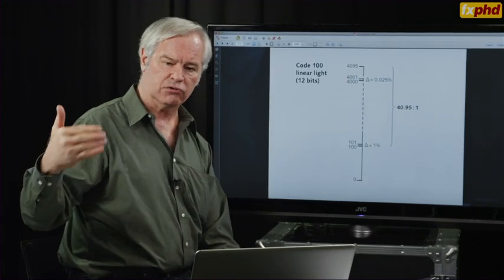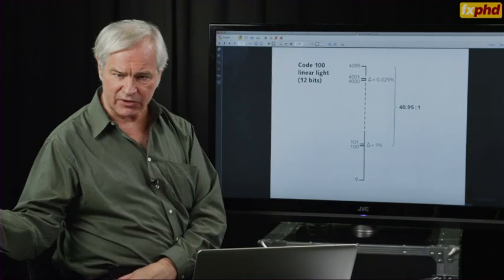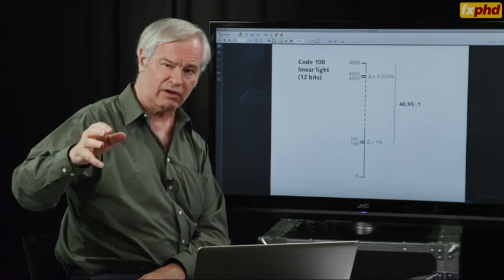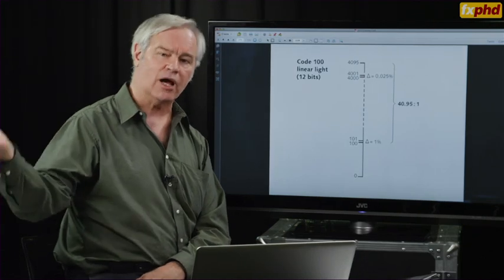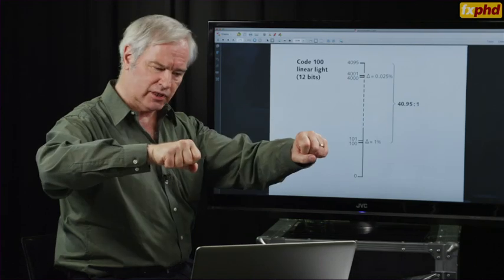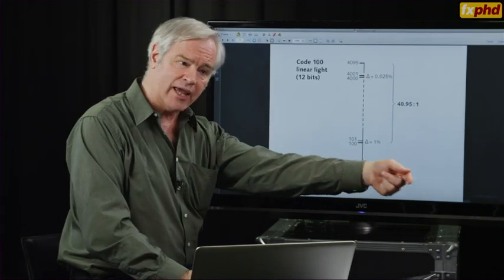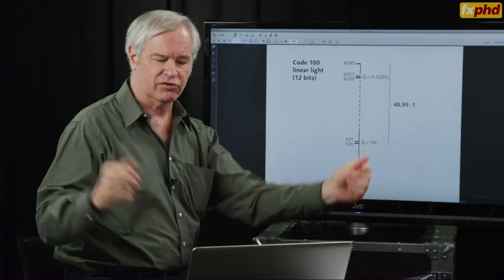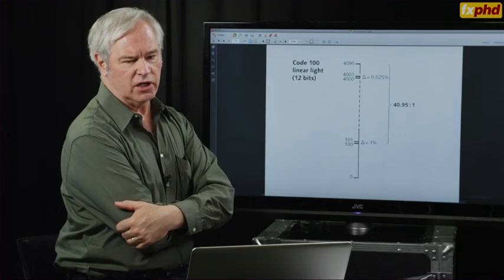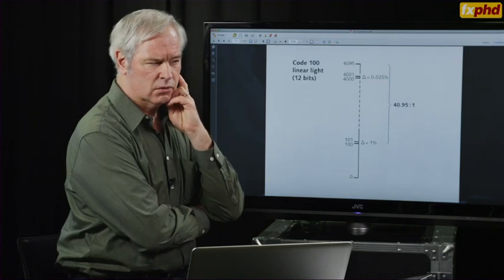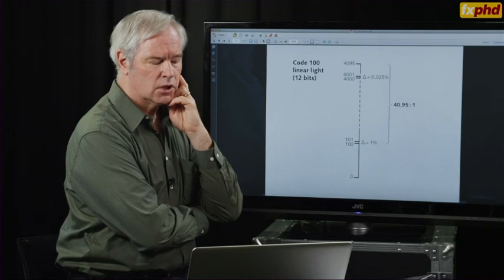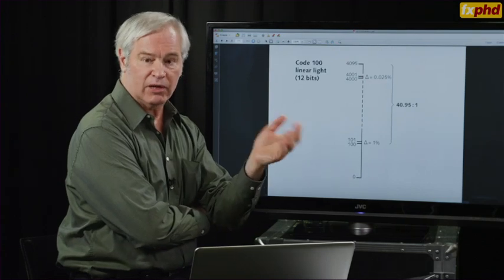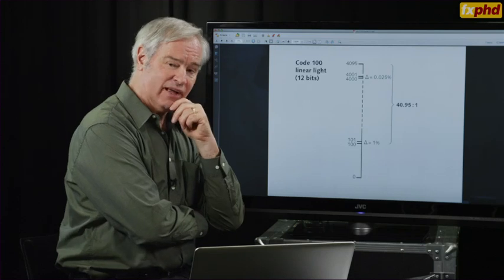So basically, historically, a video camera would use something like a 0.42 or a 0.5 power function, very, very roughly comparable to a square root, to come into a perceptually coded domain, and then the display would go out of that using, roughly, the inverse of that power function. And just recently, in 2011 or 12, HD gamma for display was finally standardized at the value 2.4.